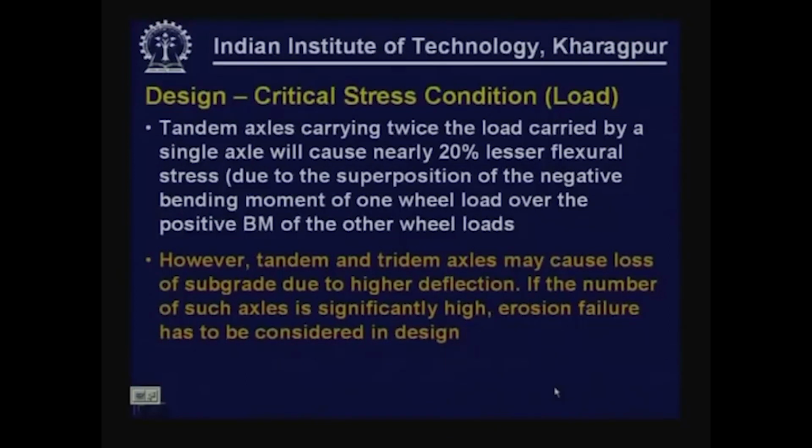So, when you have a large percentage of these multi axle vehicles, we have to be concerned about erosion failure. In India, we still do not have a very significant percentage of multi axle vehicles. So, that is the reason why IRC 58 has not taken into account the erosion failure in its design considerations.